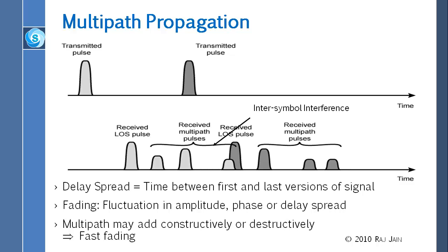Right? And why do we have this delay spread? Because the signal is going to be reflected from here. First of all, some copy will be reflected from here and quickly come here. Something will go all the way there and then come back, so that will be delayed more. Something is going far away and then coming back, and will be delayed even more. So you get multiple copies of different amplitude and different times. So basically, that is the delay spread we measure.